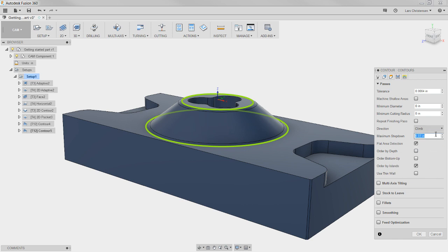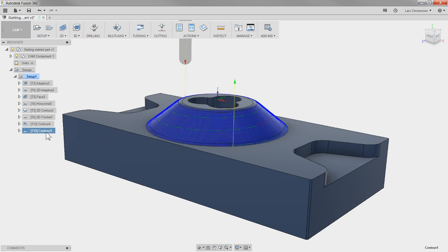So how far can you go? What should you run this with? I always tell the story about being a mold maker and programming things like this. Many times what I would do is come up with a number. So, for example, you decide, okay, let me just try, let's say, 10,000. Because there's not really any magic with this. You would go out and run that. And many times I would start machining it and just machine for a couple of minutes, then stop the machine and look at the surface finish, because that's really what matters at this point, right? How nice does the surface look?